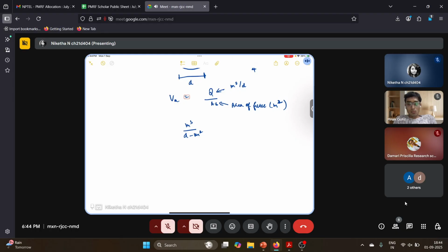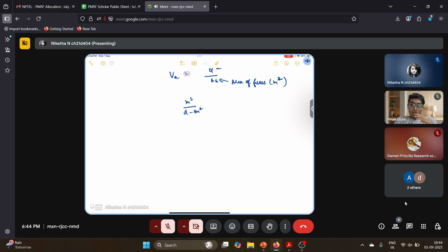So there is one disadvantage of using a filter. It's that these filters usually have pores, right? So these pores can get clogged over time. Most of the time some particle may sit and it will not move, so whatever water is incoming will not be able to pass through. So backwash must be done.